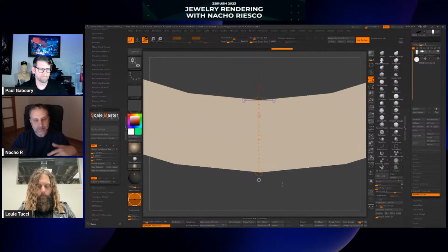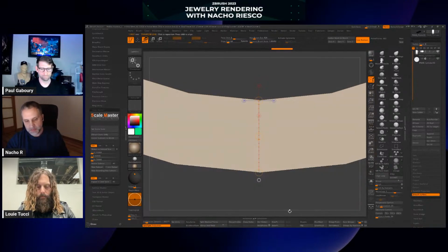So if we are having 1.5 millimeter during the manufacturing process, maybe we can find that half of a millimeter. Maybe we are going to have problems during the manufacturing process. But if we are creating a thickness of 1.8, it's going to be enough. So that means that we don't need to be 100% very precise, because we are going to lose a lot of thickness during the manufacturing process. But we need to know during the designing process that we are going to have enough material, enough metal, or enough meat to work with.